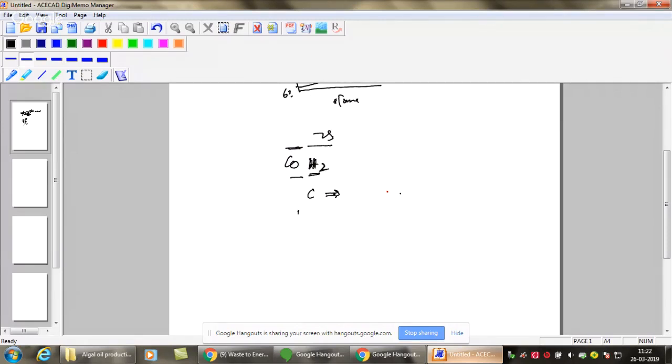So some properties like thermal conductivity, or electron generation during photoionization, or light absorption capacity vary between different gas components, and change depending upon the concentration. If we have a detector to sense this variation, we can quantify the gas composition, and that is the role of the gas analyzer.